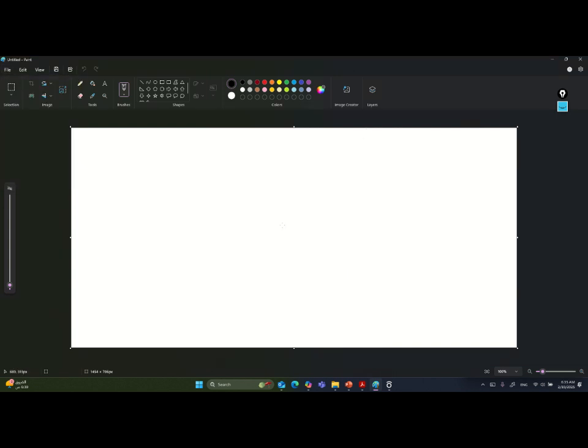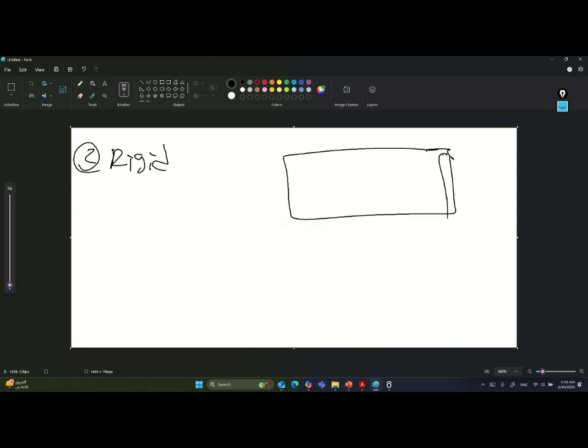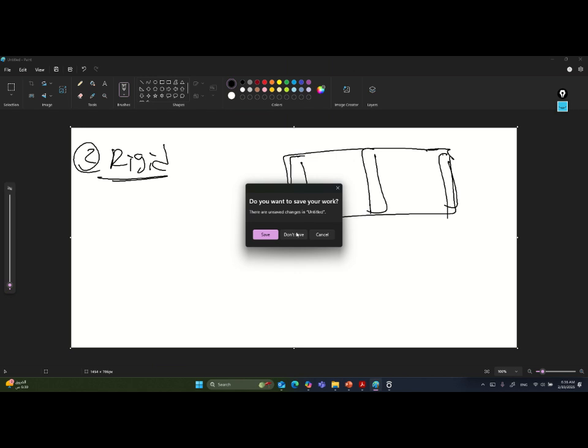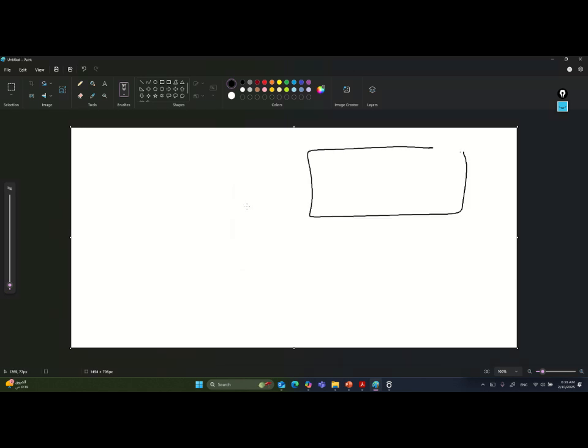The other case, if he tells me that it is rigid, so I have a rigid structure like this one. Another thing regarding the flexible, because it is the old trick in the exam: he will give you the same one, and for each shear wall he will give you a rigidity. But in the statement he will tell you I have a wooden panel.